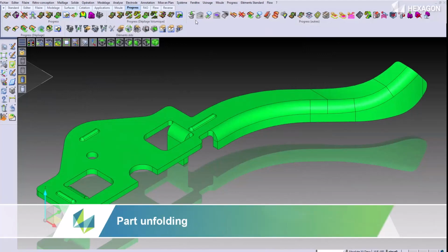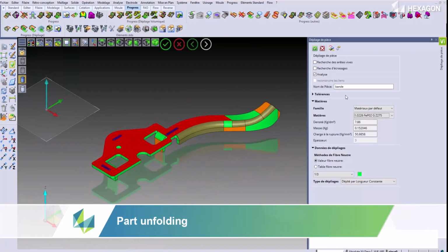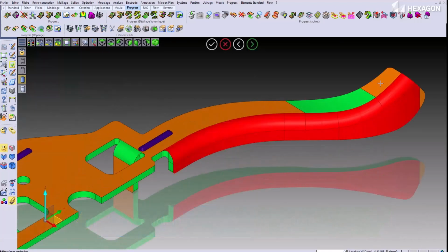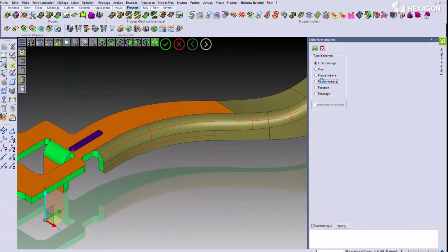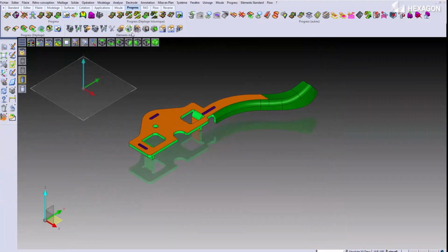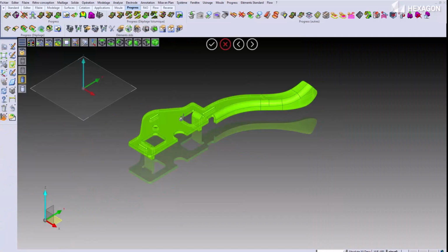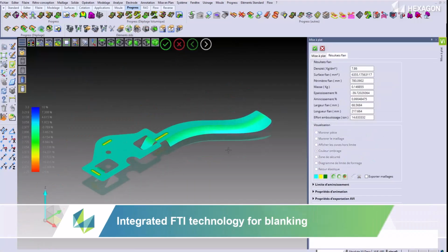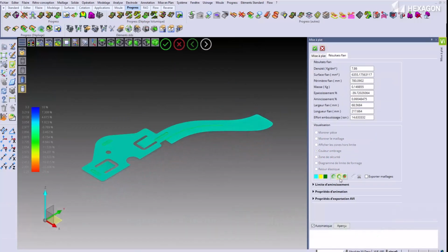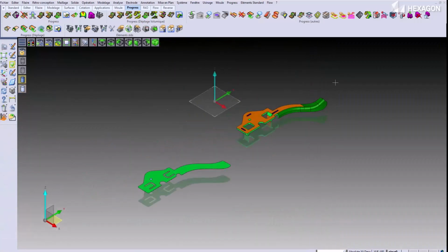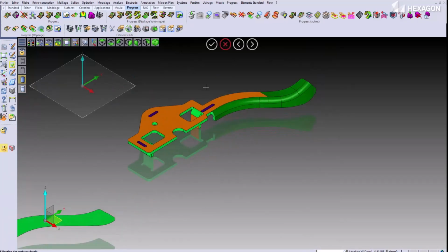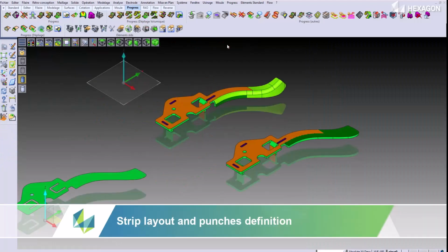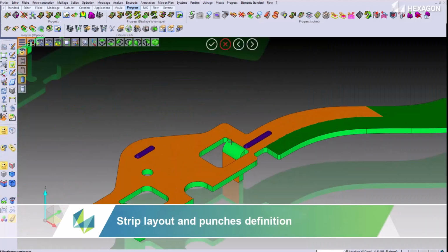The stamping process planning starts with an unfolding of the 3D model of the stamped metal part to produce a flat pattern or blank shape. The final part must be developed or unfolded step by step from its initial form until the exact initial 2D shape is achieved. VISI uses Hexagon's FTI forming suite, scientific physics-based technology, to develop accurate blank shapes based on forming process and material properties while accounting for stretch and deformation due to induced strains realized from the 3D product geometry.